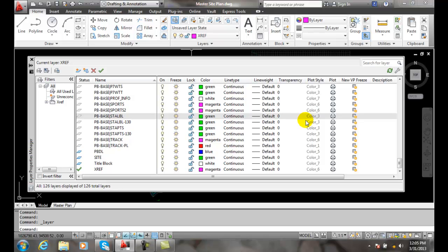So to manage all the different names of things, AutoCAD will place a pipe symbol, that's this vertical bar symbol here, in between the layer name and the drawing name, the X reference file name. So I've got the X reference file name and we've got the layer name here. And in doing so, it doesn't allow us to make it current, so we can't draw on them. And also it allows us to freeze and thaw any particular layer that's X referenced in, or we can turn it on and off, or we can lock them or unlock them.